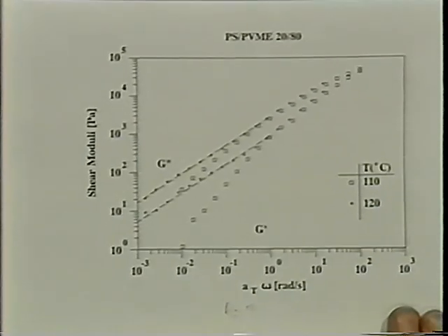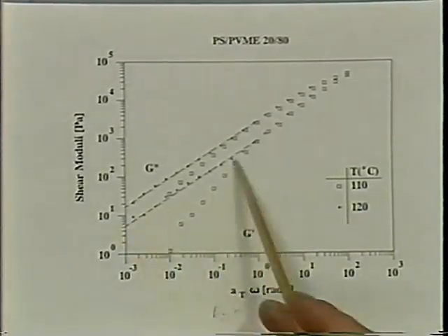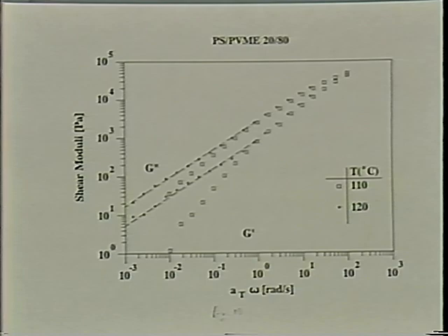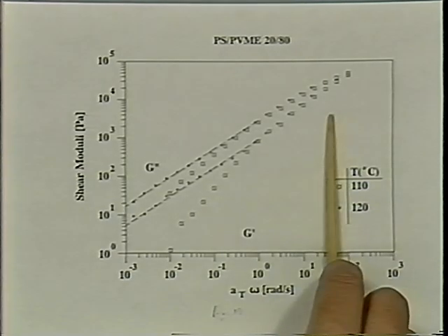At different composition, this is at a lower polystyrene composition. It's the same general evolution. Only at low frequencies we see something. At higher frequencies, the phase transition is not visible. So if you would perform dynamic mechanical experiments at a rate which is too high, you would not detect any phase transition in rheology. Your conclusion would be that rheology is insensitive to phase transition, while light scattering or some other technique which gives you the divergence of some large fluctuations would be sensitive.